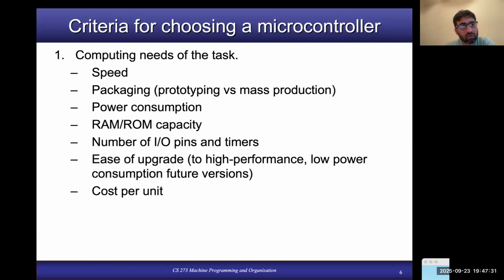Similarly, can you place the amount of data which will be processed or produced by your code in the RAM of the given microcontroller? If yes, then you can select it. If not, then you need to look for another microcontroller which is good for your purpose.